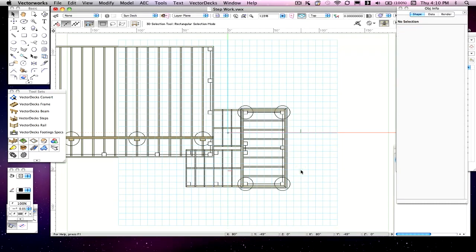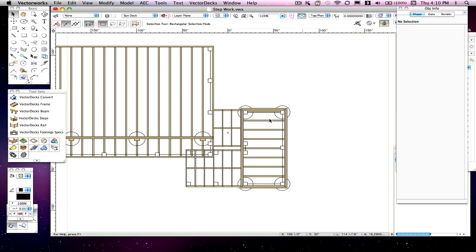And as you saw, it drew that very fast. It replaced that square landing with the step coming out the front with this rectangle landing, with this U-shape, with the steps going back in this direction. Now the reason why I drew it that fast is I had turned off Draw 3D and we're in a top plan view. It's very helpful to work in that view. It'll just speed your designing process up a bit. Then when you're ready, you can just click on that 3D and it'll draw everything in 3D very fast.